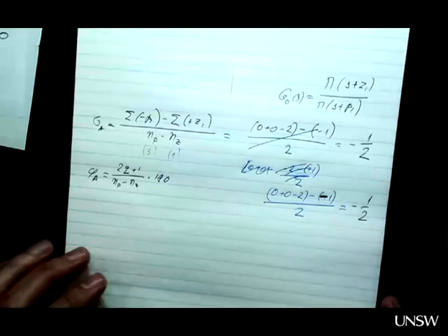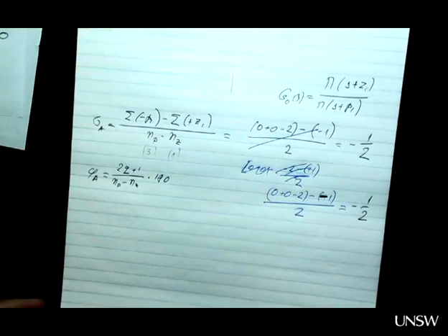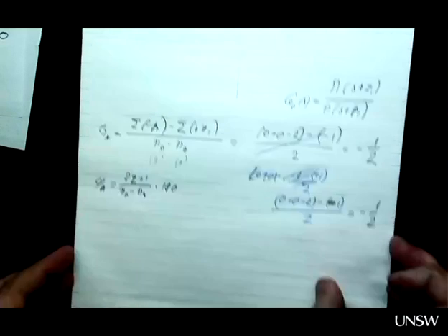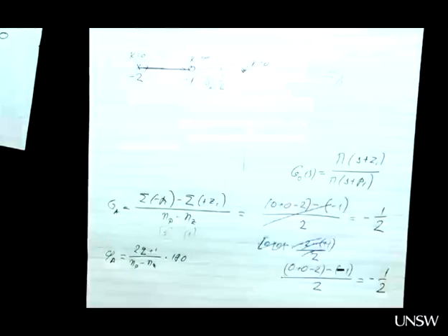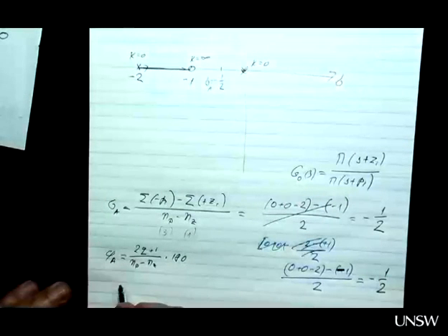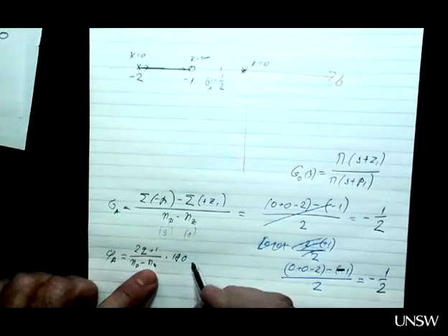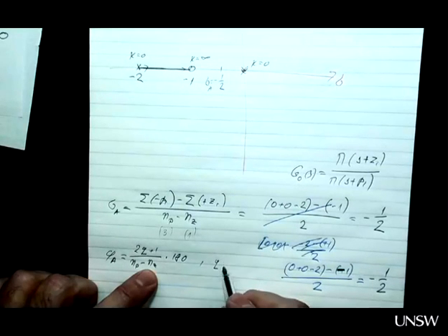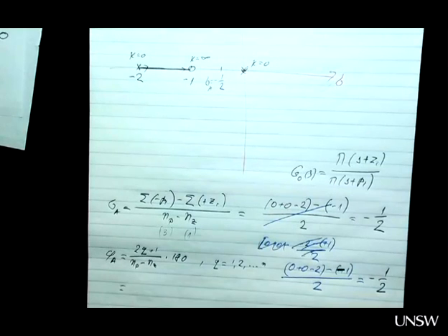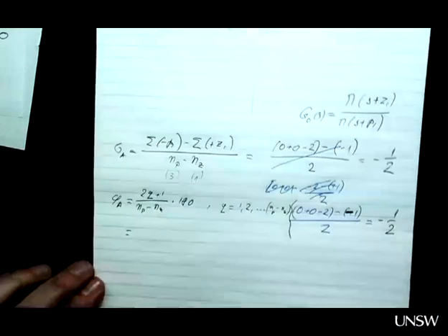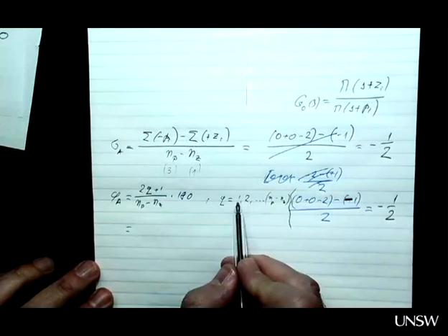Okay, so it's minus 1. So definitely the centroid is minus 1. Let's get the angles. Apart from that, we need to know what Q is. Well, Q is an integer, actually, this thing is NP minus NZ. Okay, so we start changing Q from 1, 2, 3 until these angles start repeating.